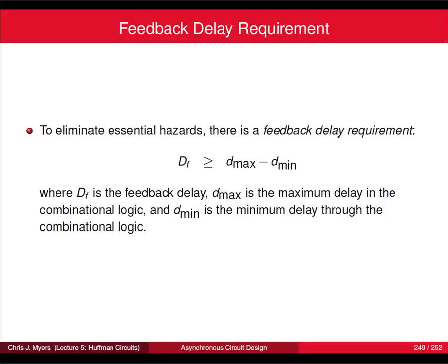Yeah. So all these are done in logic, right? So at the transistor level, you don't make any modification to the feedback loop. You do all this delay in the logic, so that's why you introduce this delay between your feedback and your actual output. The way you create the delay in logic is you'd add a chain of inverters. Yes.